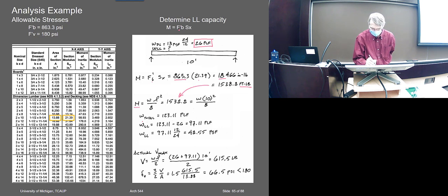And that is the moment at the center line, and then that's equal to WL squared over 8, and I'm trying to find this W. Okay, the part of the W I already know is that 26, so the total here, okay, I just solved this for W, right?